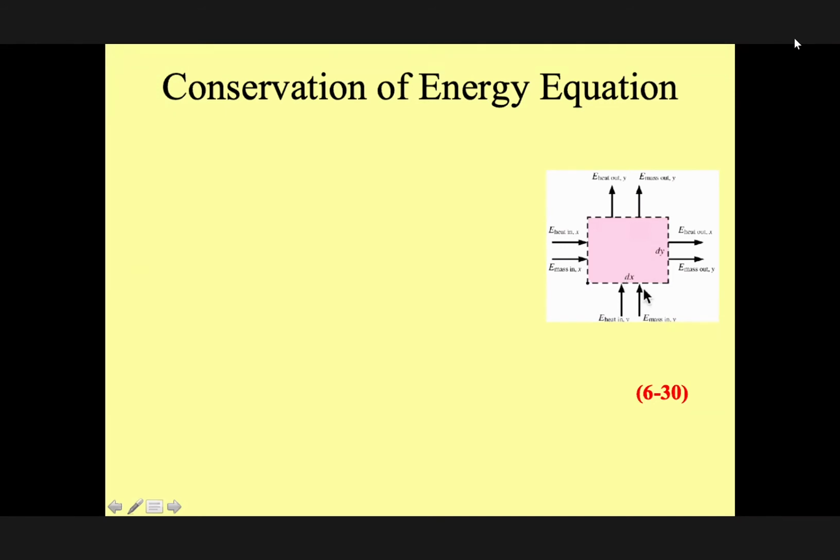And also we assume, because the fluid is moving, that there is some energy passed through mass transfer, okay? As mass moves, it takes some energy with itself, mc delta T. Again, we have a mass here in this direction, the fluid has a certain velocity and moves in this direction, it has a certain temperature. When it gets here, it is at another temperature. Therefore, we're trying to take into consideration all the possible modes of heat transfer. Motion of the fluid, conduction, convection, everything comes together, okay?